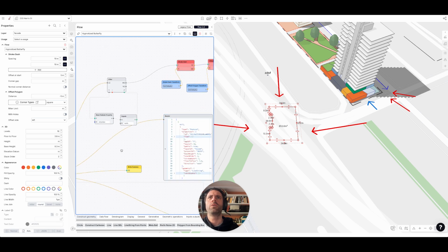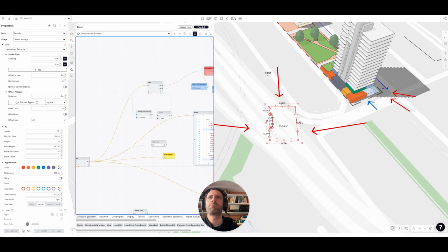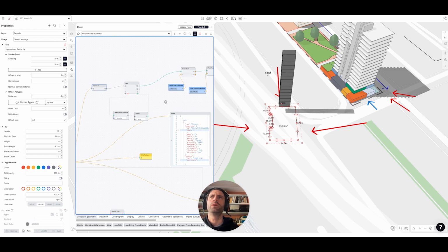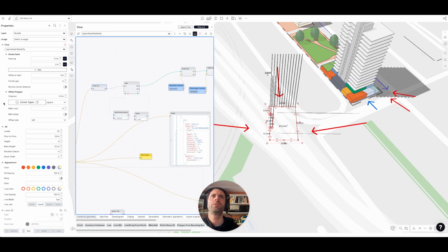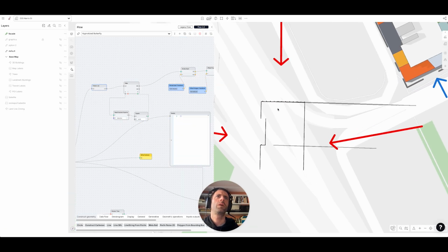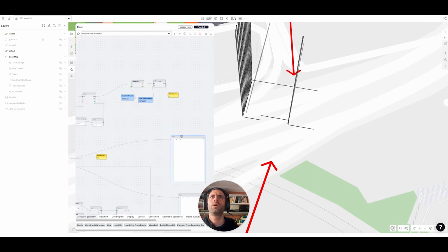Okay, and this map is not going to work because you can see this is a nested list. Okay, fantastic. There we go. We got it. Now, spacing is 0.12, and the offset at the start is 0, and this is 0.3 to the left. Okay, and so that's our north-facing facades. That's fantastic. And now we should do our west and east facing facade.